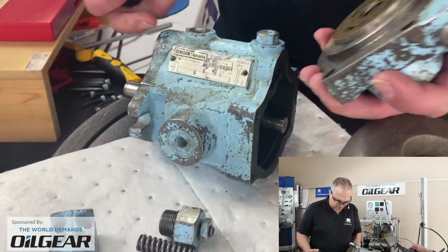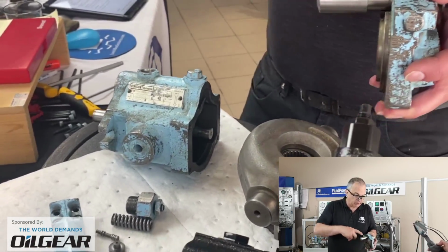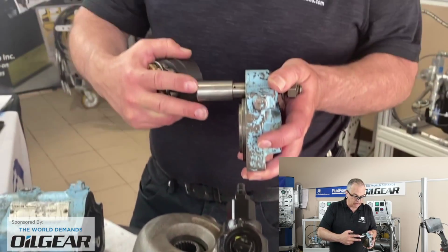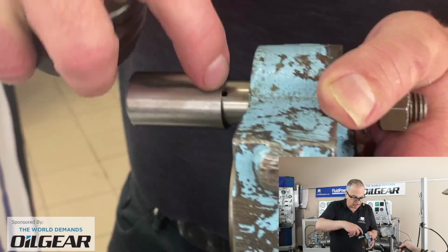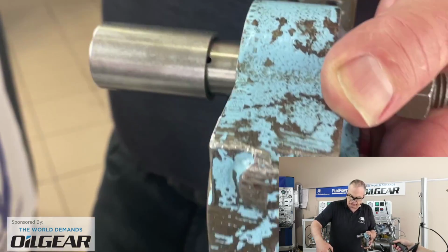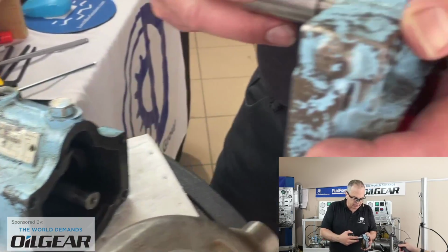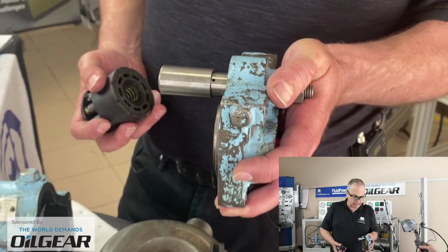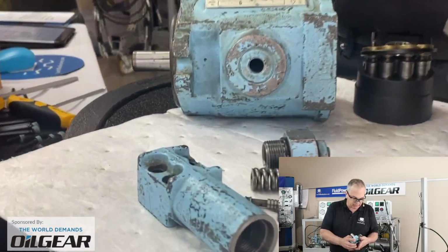It's a fairly simple, basic, straightforward design. Oh, there's that little maximum stroke limiting orifice, fairly large, right? So all of a sudden you get to off stroke and your case drain flow, because this is draining into the case, is very high. You've uncovered that port. You've gone as far as you can, and your pump is at the 0 degree stroke angle.